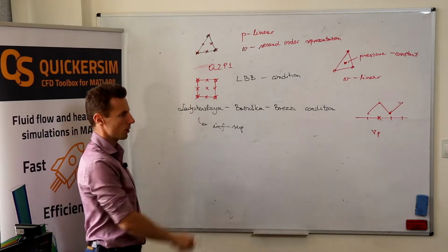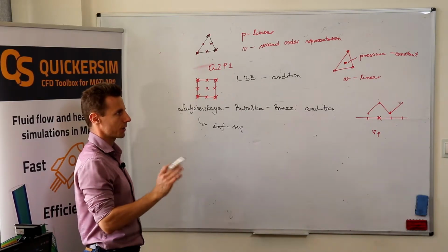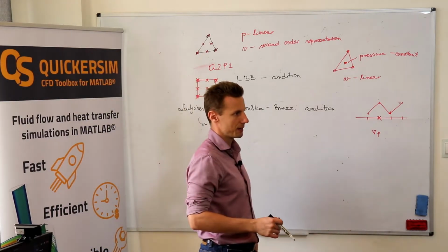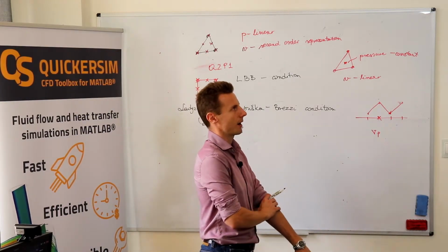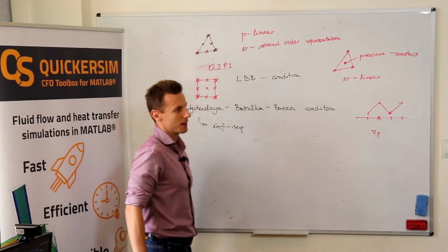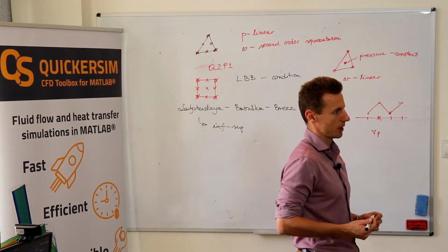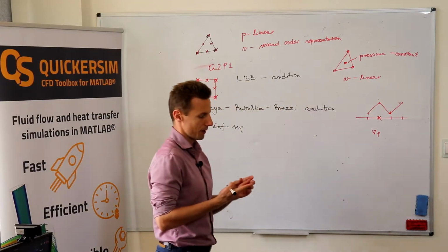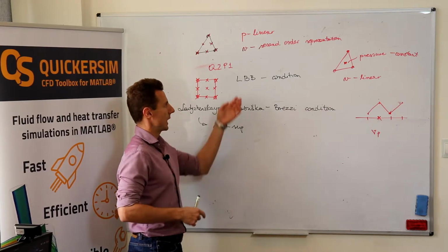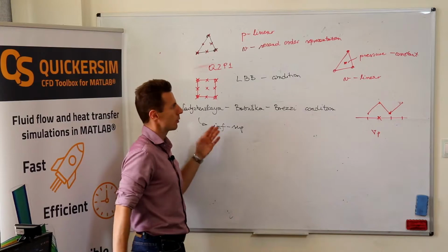And if you go to the derivation or to the proof, you will find what kind of equality or inequality must be fulfilled for your, I think, the gradients of the velocity function times something. And you've got a nice relation to check if it holds or not, but I don't want to go into the derivation. LBB condition, infimum-supremum condition, these are two names that you should remember.